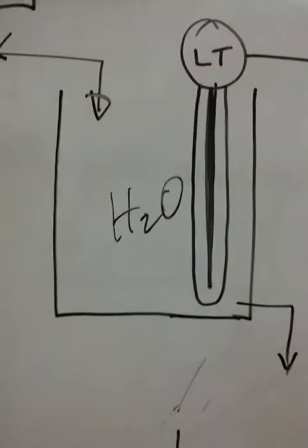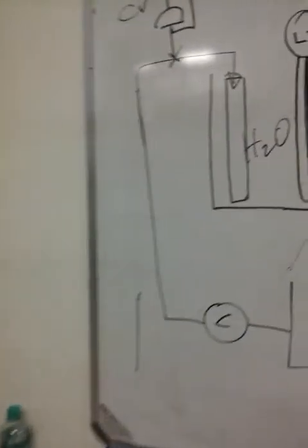The capacitor is always made of 2 plates. So to make a capacitor, we had to add 1 metal probe. Why do we add that? Because our tank is plastic. If this was a metal vessel, there was no need of adding the extra probe.